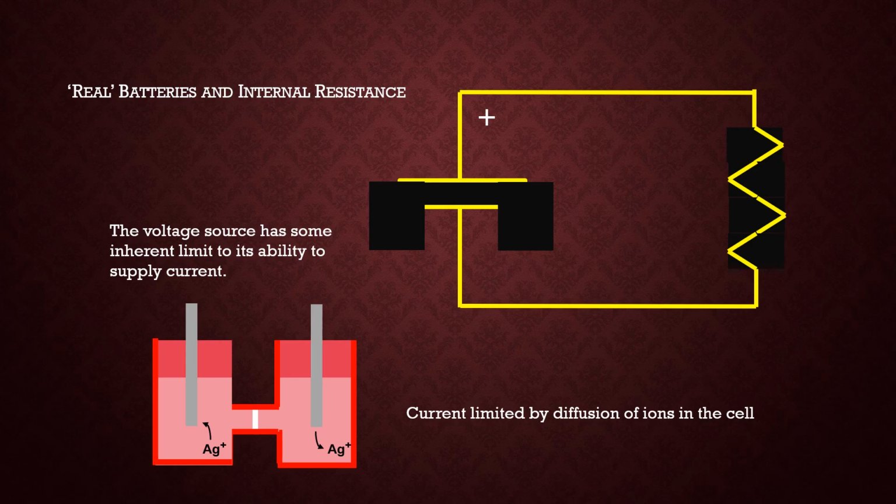So for example, what I'm driving at is if you take that resistor out of the circuit that I've drawn and just short circuit the power supply, in other words, put a conductor attaching the top to the bottom, copper wire, that would be a short circuit. But the current would not obviously go to infinity, because the ions that have to be either the production of charged particles, namely the electrons, that is kinetically limiting. So there's going to be a limited current. You're not going to go to infinity. So this is referred to as the internal resistance of the device.